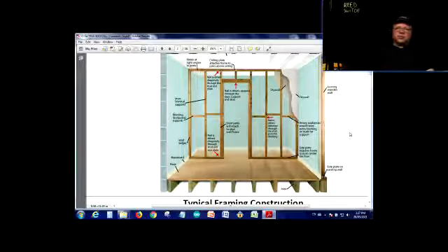But that's not always the case, because sometimes you're going to have to deal with construction that is already done, like additions or something like that. And sometimes, if somebody wants things to be done a certain way, and you know that it's not really possible, you're going to have to just say, no, I'm not going to do it. Because not only could you get obstacles in the form of horizontal studs or noggings, you also run the danger of puncturing plumbing or electrical wires that already exist over there.